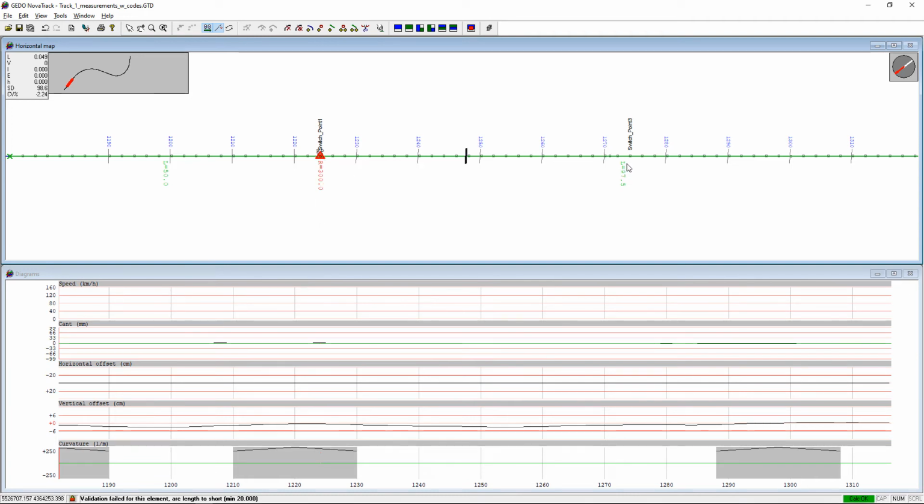And then we can approach the switch point 3 in the same way. So again, I select from the toolbar insert radii element. We click exactly over the switch point 3. As the snap function is active, we don't need to worry that it will not be inserted where it has to be.